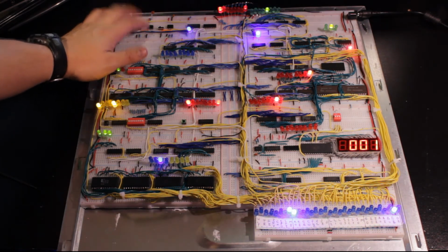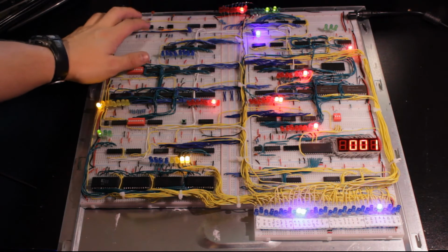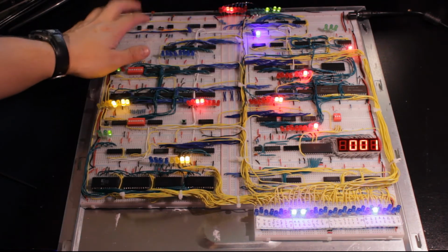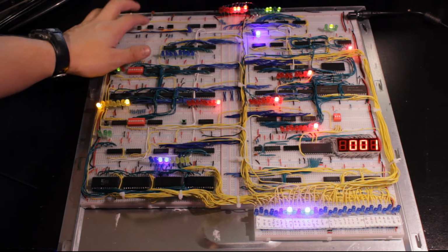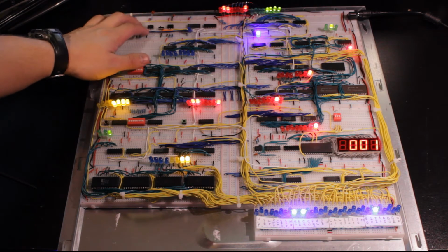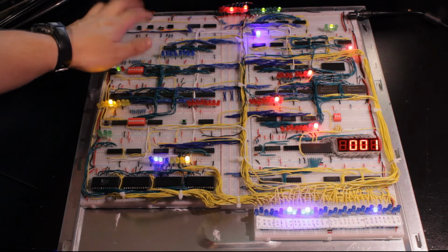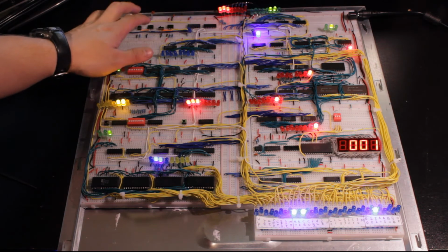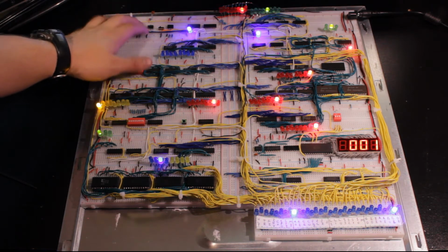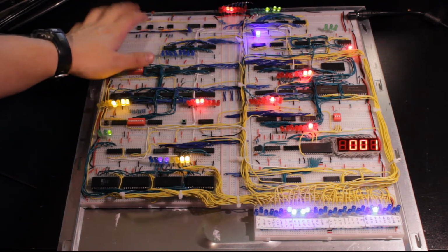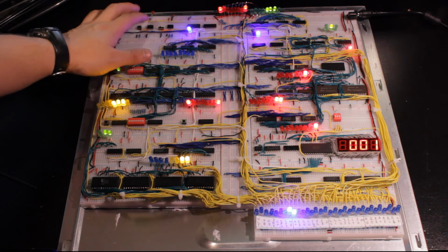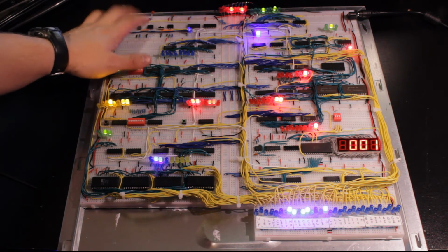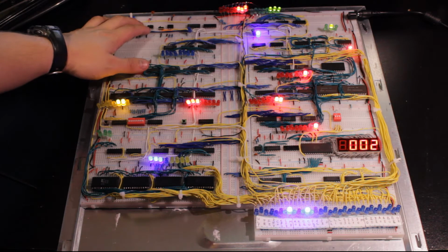So I'll go through it slowly, and we do the addition, we got the 2, we store A, we do the subtraction, we got the 1 again, we store it, and then we're going to do not the conditional jump, but the unconditional jump back to the output instruction, where we had another 1. We repeat this process, we do the addition, we get a 3, we do the subtraction, we get a 2, we store that, and then we're coming around again and we output the 2.